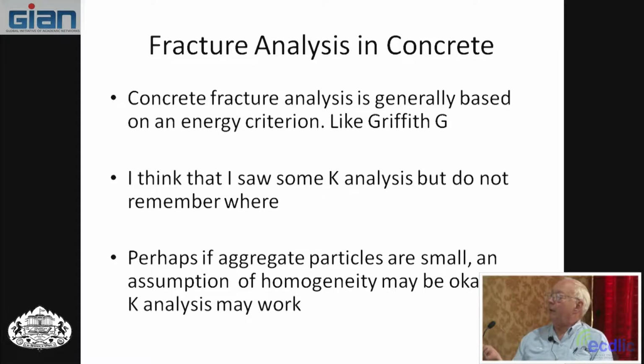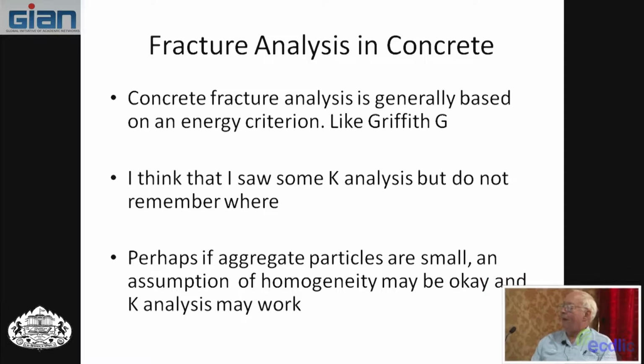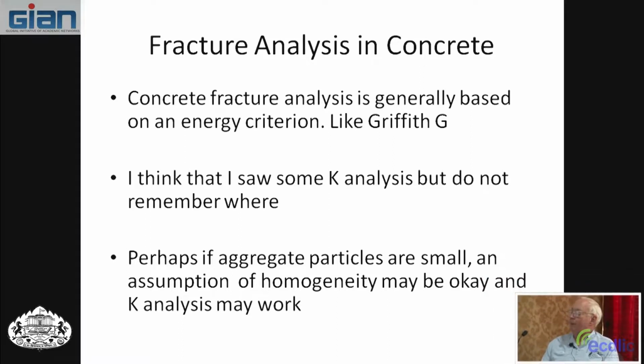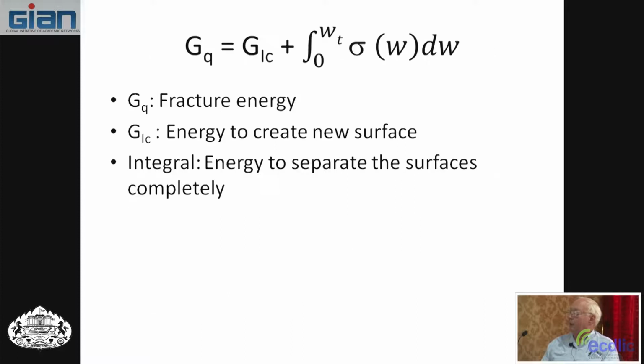So, fracture analysis in concrete. Concrete analysis is generally based on an energy criterion. I think I saw some people doing K analysis, but I can't remember where. If aggregate particles are really small, then perhaps homogeneity is not a bad assumption, but in general the homogeneity assumption doesn't work and the K analysis doesn't work, so more often you have energy analysis.